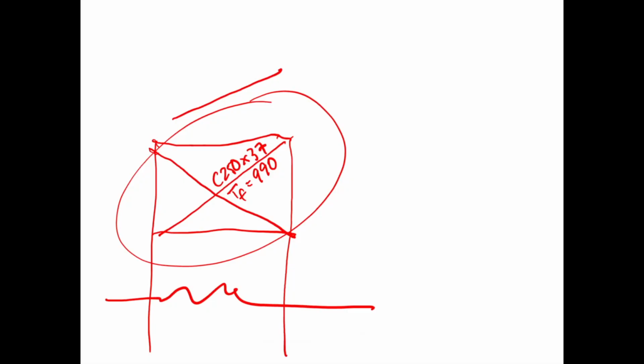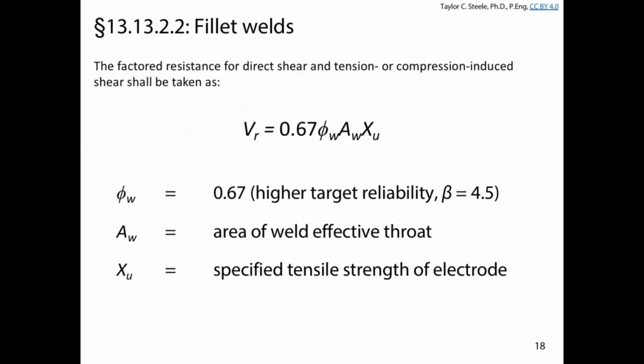Okay. So, the fabricator decides, I'm going to weld it. And when we look at welds, we've looked at the strength of welds, right? The first job of the engineer is to specify the size and the length of weld to satisfy the shear strength limit states for the actual weld material. Okay, so I need to make the weld strong enough.